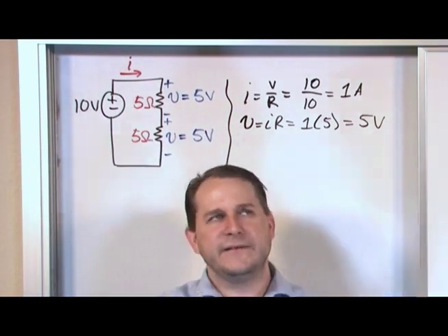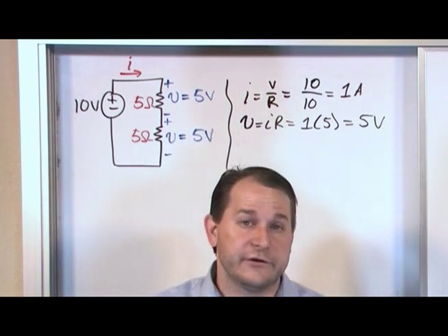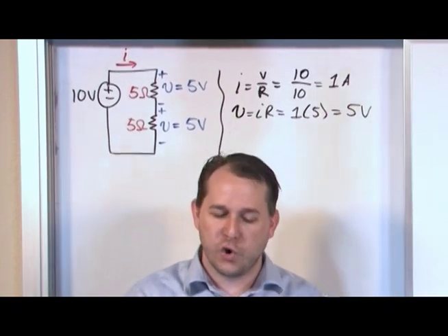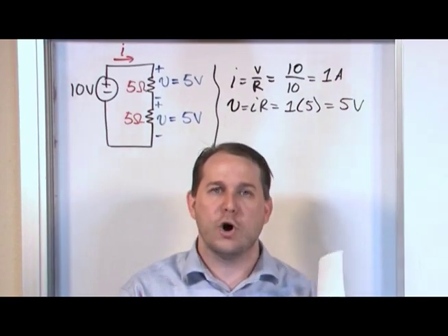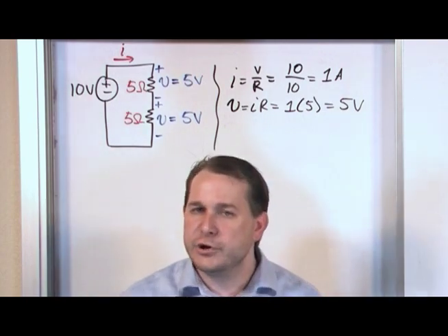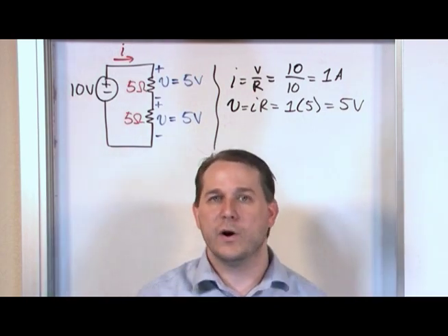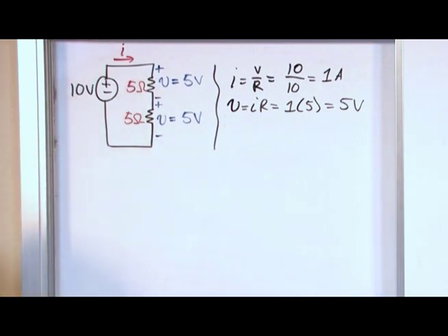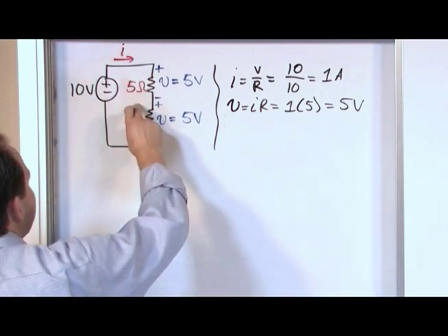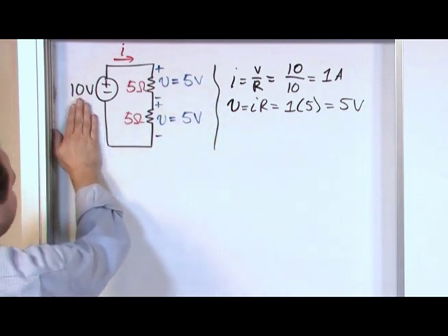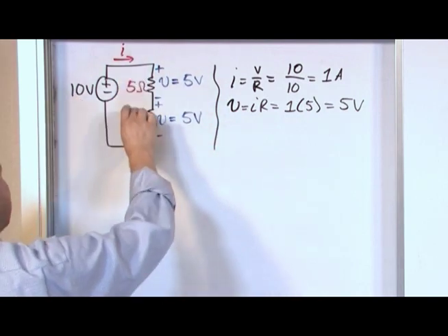You see, I'm not inventing something else, saying, oh, this is a special voltage divider, you just have to memorize it. It's not like that in circuits. Everything makes sense from the core values of Kirchhoff's laws and Ohm's law and the fundamental things we've learned. So there's nothing really new here. It's just an application of what we already know and some intuition that comes as a result. So this is the bottom line. In this particular case, if I want to divide this source in two, I would choose 2 equal resistors.